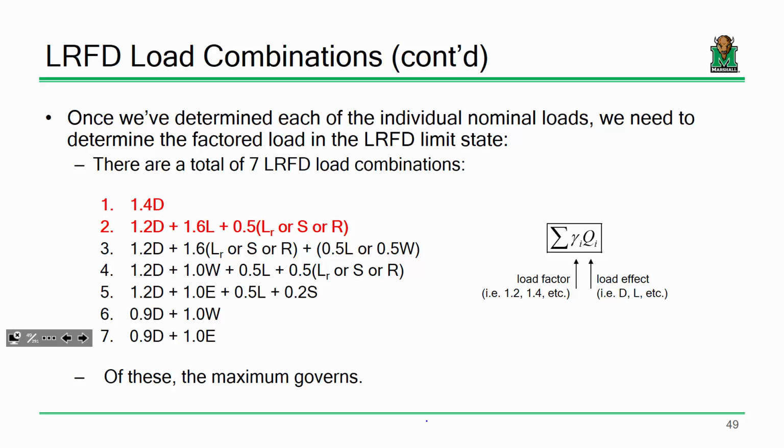But if I then take this table and sell it to some end user, I don't know what they're going to use it for. They can put whatever they want on it, right? So I have more certainty associated with the dead loads, so I don't need to bump those up as much. The live loads, I bump them up a lot more. Okay? Make sense? Anybody have any questions about that?